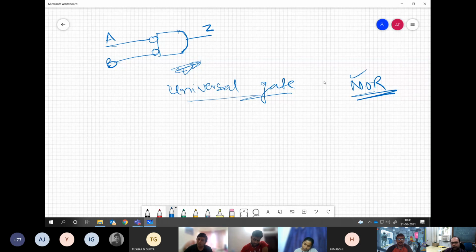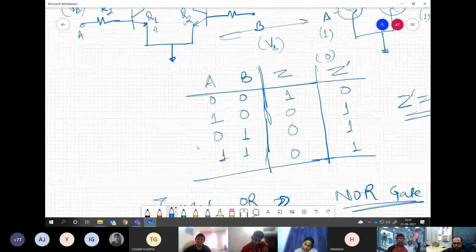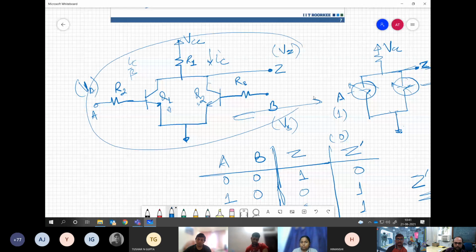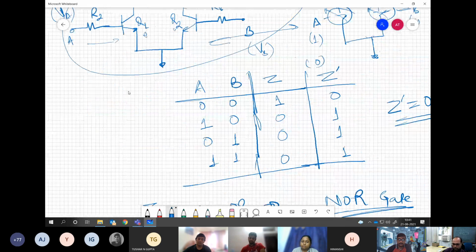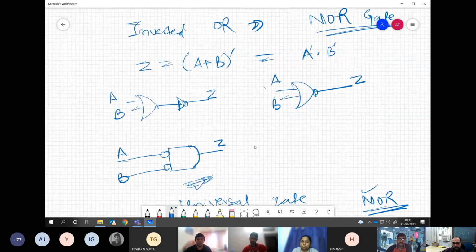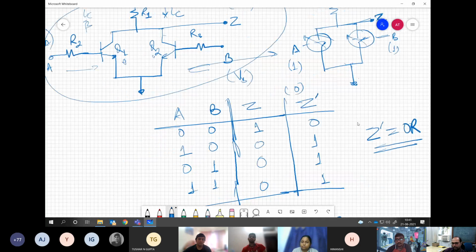So these are one of the first gates which were realized using the RTL logic. It worked for some time, then people had to move to better logic designs, obviously, because there are so many constraints in this. We have to ensure how much current is drawn, how much base current we have to pump in, and all that. Because of all these restrictions, slowly people started migrating to other logics. Understanding my point? But still, for some time it was used practically for realizing gates and circuits.